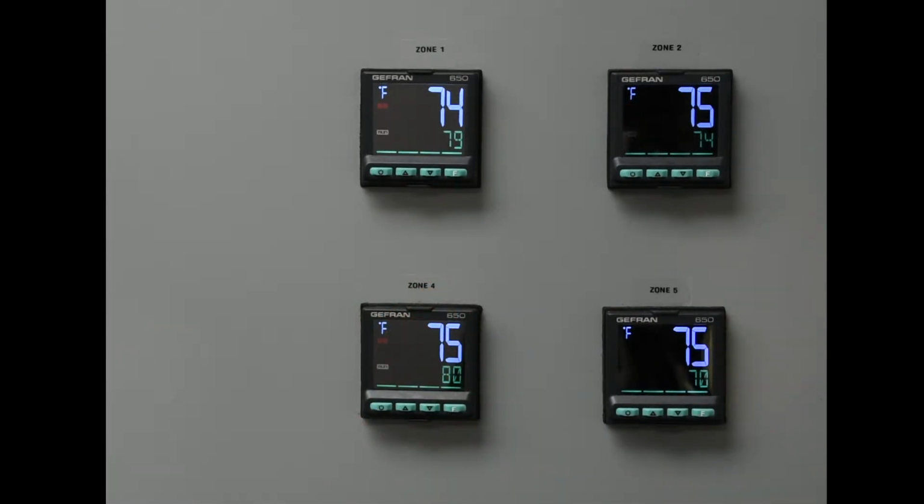The controller is designed to use PID logic to limit overshooting the set point temperature. This can be accomplished by auto-tuning. If you wish to manually enter the PID values, refer to the 40524-04 programming manual on our website. The PID tuning can also be turned off so that the controller acts as a simple on-off temperature controller.